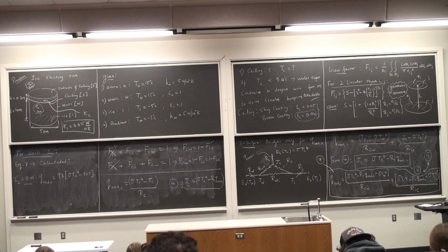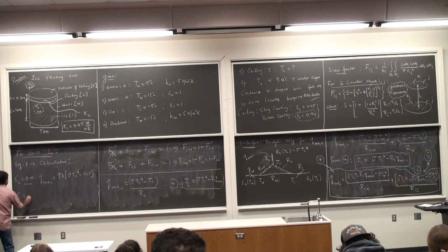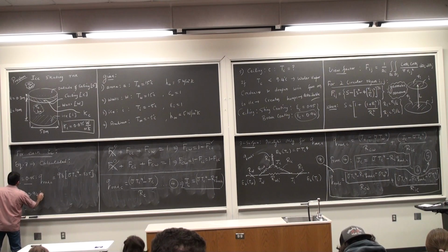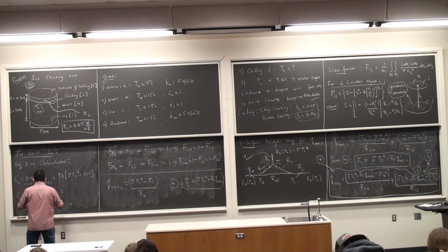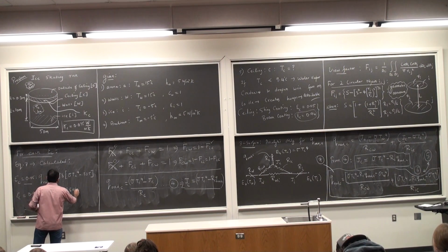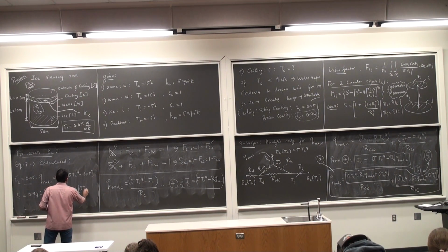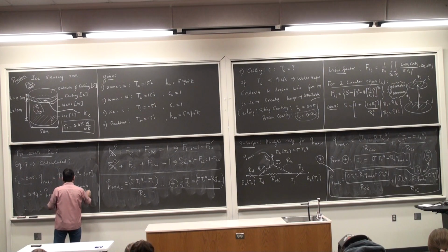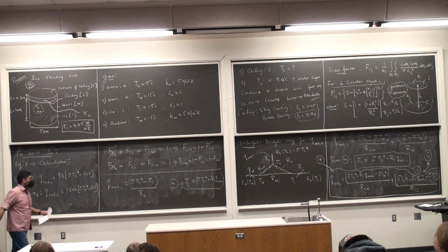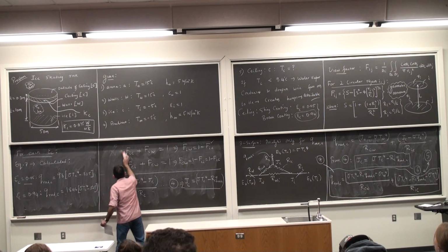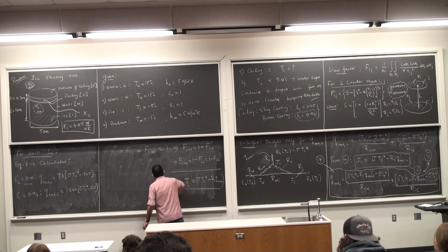All I'm doing is taking all of the terms containing Q radiation C, combining them together and writing everything in terms of Tc. And for epsilon C of 0.94, Q radiation C becomes 1846 Tc to the power 4 minus 325. Once again, that's the same thing. And then I have equation 3, very last step.